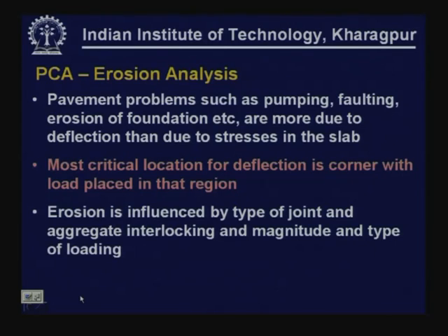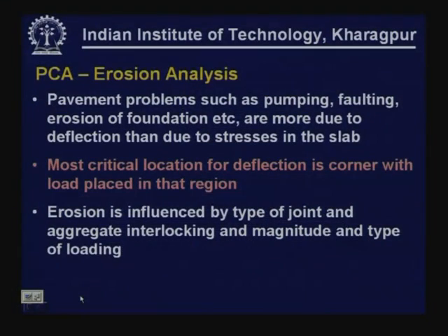Coming to erosion analysis, that is considered in PCA analysis, pavement problems such as pumping, faulting and erosion of foundation etc. are more due to the deflection than due to stresses in the slab. Deflection is the consideration that we have to be concerned about. If there are more deflections, there is going to be more pumping, more erosion, and more faulting problems are likely if the slabs deflect more. The most critical location for deflection obviously is a corner because of its discontinuity in two directions. That is when the load is placed in the corner region.